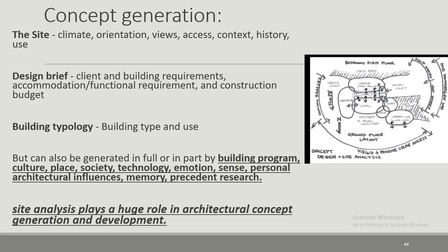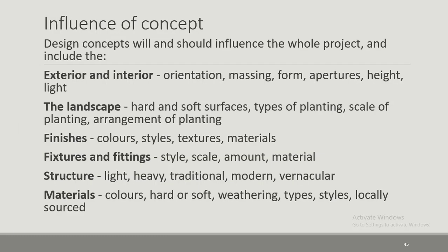However, site analysis plays a huge role in architectural concept generation and development. Design concepts will and should influence the whole project, and include the exterior and interior, including orientation, massing, form, apertures, height, light. The landscape, both hard and soft surfaces, types of planting, scale of planting, arrangement of planting, finishes, colors, styles, textures, materials. Fixtures and fittings, style, scale, amount, material.